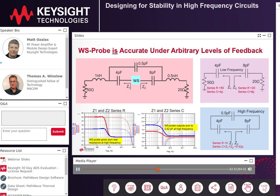The sum of the 3 capacitances is equal to 0.42 picofarads by inspection. And you can call this the loop impedance. If you look at the old S probe prediction of the bidirectional looking series resistances, they go into negative values above 100 gigahertz. And this is completely non-physical. The new WS probe accurately returns 0 resistances in the source and load looking directions.